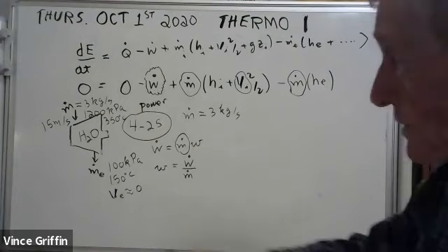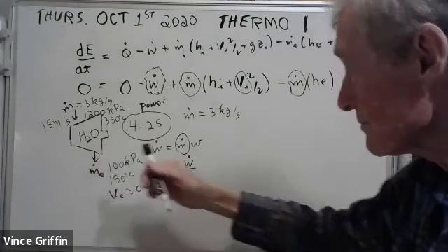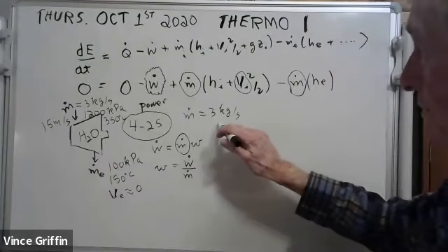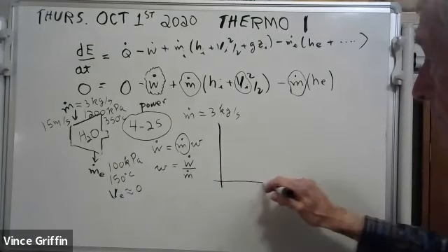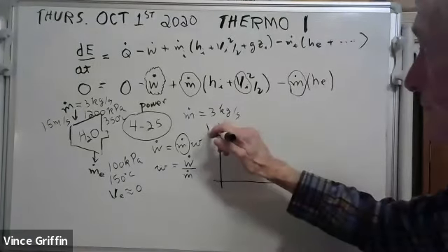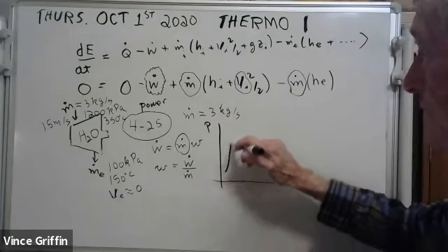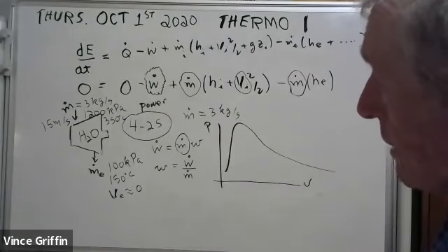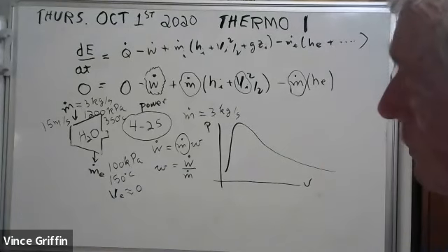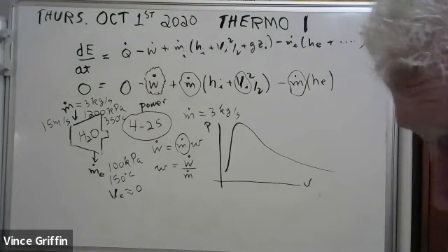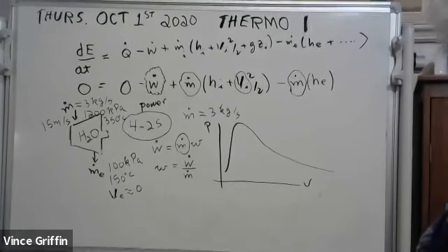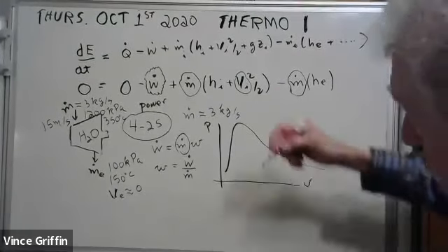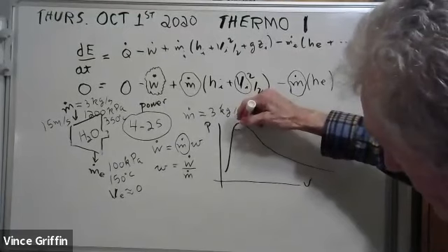Well, what's next? We did our device sketch. And then, you know the drill, we have to do a PV diagram. It's water, so you know it's going to look like that. Now help me find 1200 kilopascals, 350 C. Well, see, 350 C is way the heck up here.